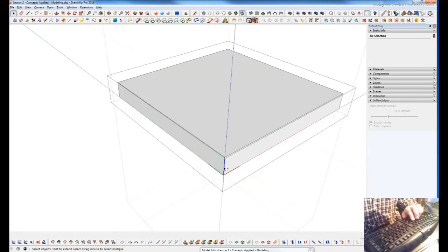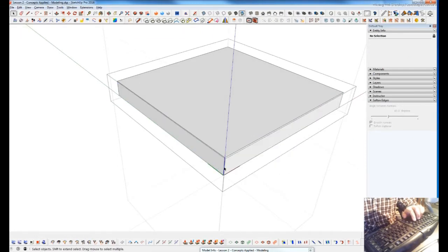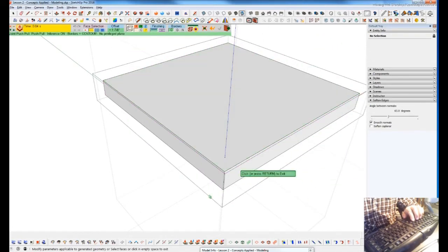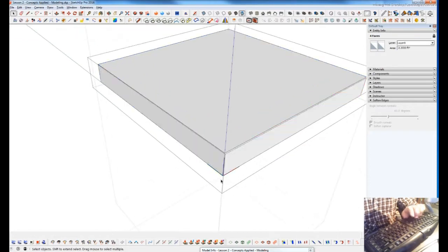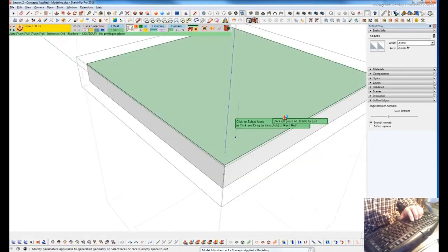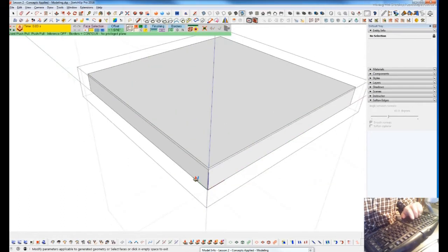And when you get into manipulating, it's just a lot faster to do that, and then use my keyboard shortcut for joint push pull and select everything, joint push pull, and then I can pull all 4 of those faces out at the same time. So it's very quick. I didn't have to move the camera at all. That's Shift Q, and then my shortcut for joint push-pull. I'm able, without moving the camera, to pull all 4 sides of these at the same time.